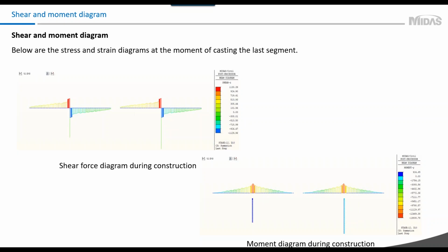And as you know, in segmental bridge analysis, we also have to consider the forces that happen during construction. Those forces tend to be the most critical ones, because those are usually the highest forces, at least moments and shears, that the segments are subjected to. Construction sequences involve traveler, formwork, as well as wet concrete, prestressing, and construction loadings. Since all those things happen at the same time, we have to find a way to consider them all during the analysis of the bridge.